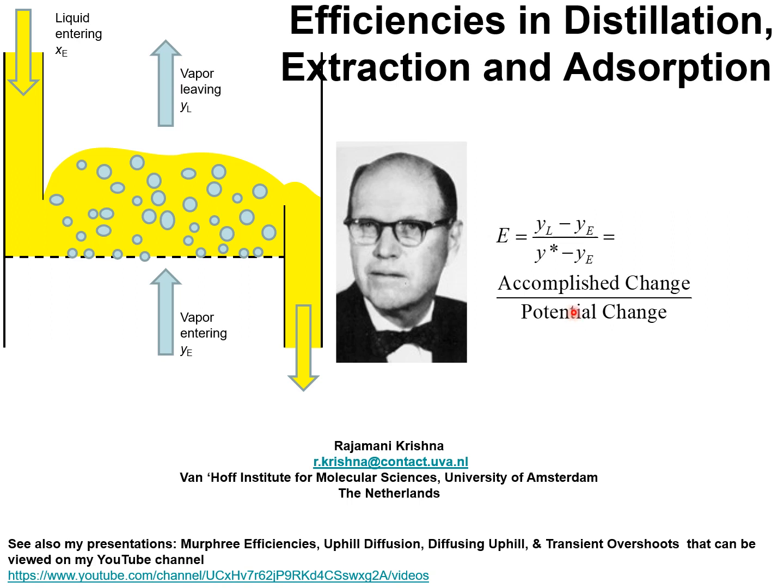For a binary mixture, since the mole fractions add to unity, the Murphree component efficiency of component 1 must equal that of component 2. This equality is no longer required for mixtures containing 3 or more components.